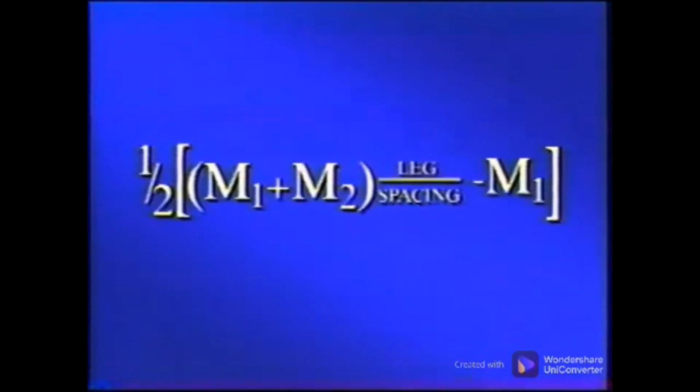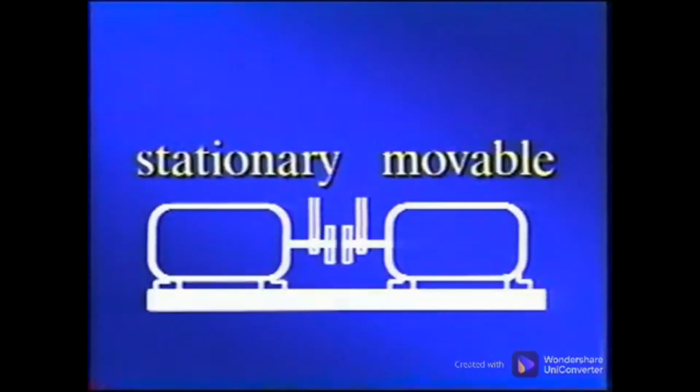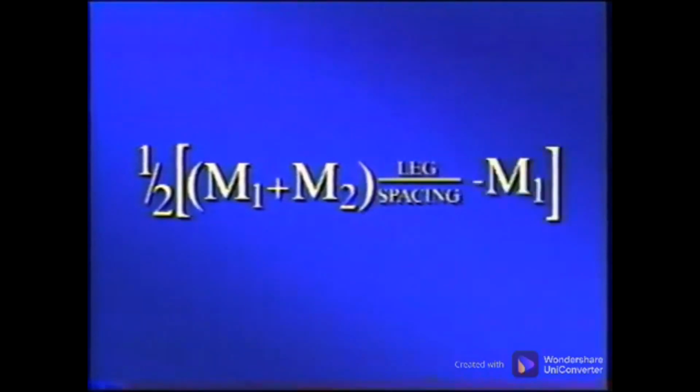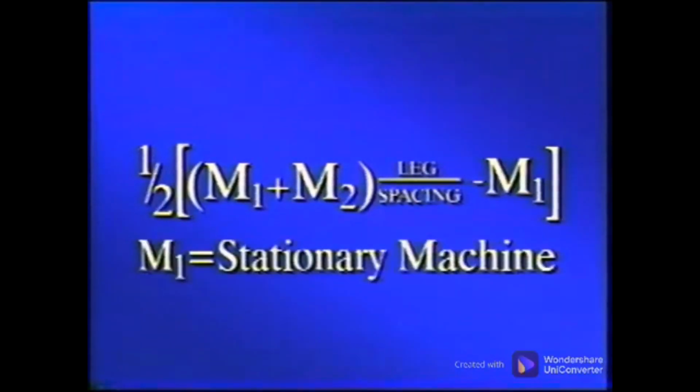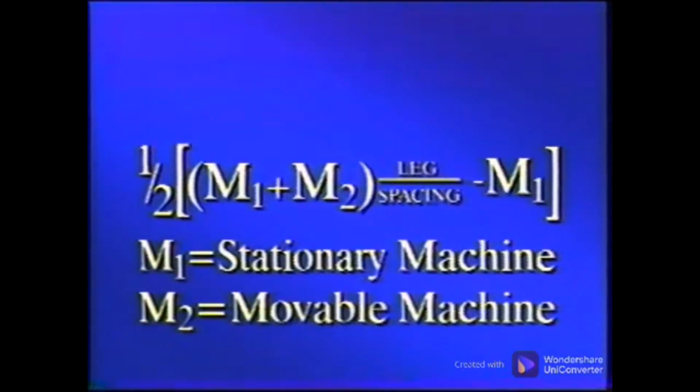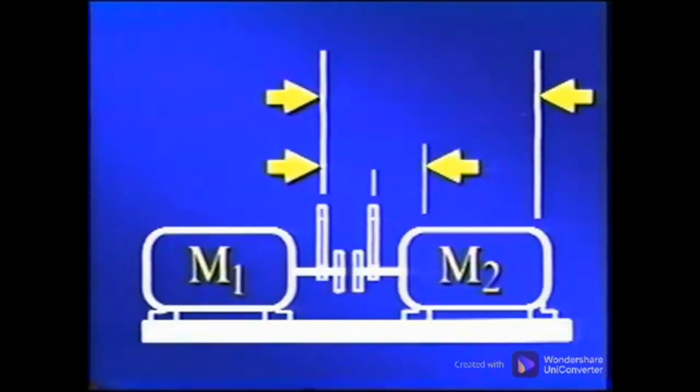A good method to calculate the machine moves is the formula method. This method is based on selecting one machine as stationary and the other as movable. The formula for the move is 1/2 the quantity of M1 plus M2 times the leg over the spacing minus M1, where M1 is the reading at the stationary machine and M2 is the reading at the movable machine. The leg is the distance from the location of the stationary machine reading to the leg to be moved, and the spacing is the center-to-center distance of the dial indicator brackets.